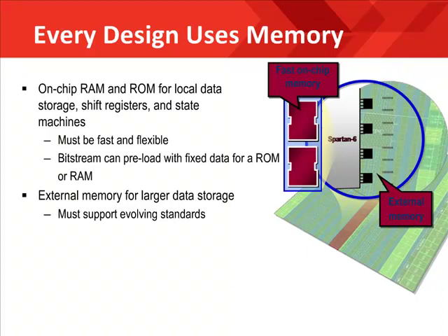All of Xilinx's dedicated memory resources, that is, distributed memory and block memory resources, can be preloaded with data so when the FPGA is programmed, they already contain the memory initialized. And since these resources support both large and small memory construction, they only use the resources necessary for the size of memory you need to build. So they are both fast and flexible.